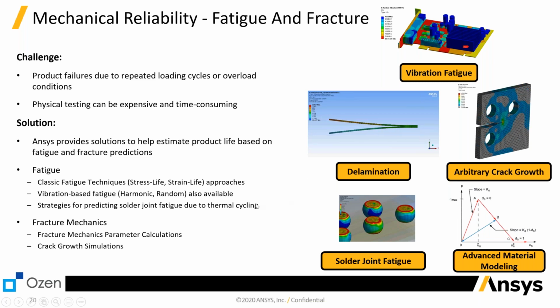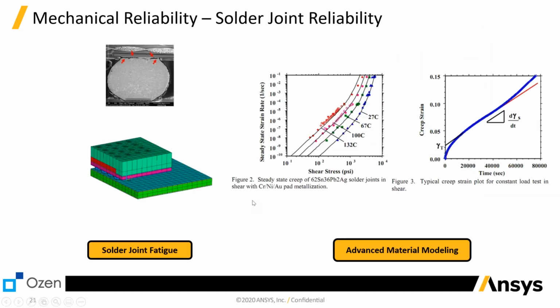So, you may say, why is this important? Once it's cracked, it is cracked. But the thing is, solder joint connections actually start cracking in the first 10% of their life. Yes, the first 10% of their life, they start cracking. Of course, it depends on the package. I'm not saying every single one of them, but in some cases solder joint connections spend 90% of their life in crack propagation. So that's when you start noticing a degradation of your electronic device. But this can all be predicted.